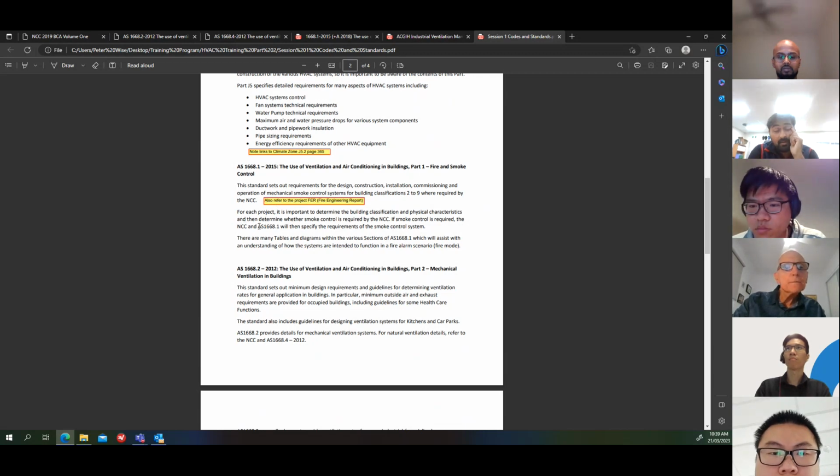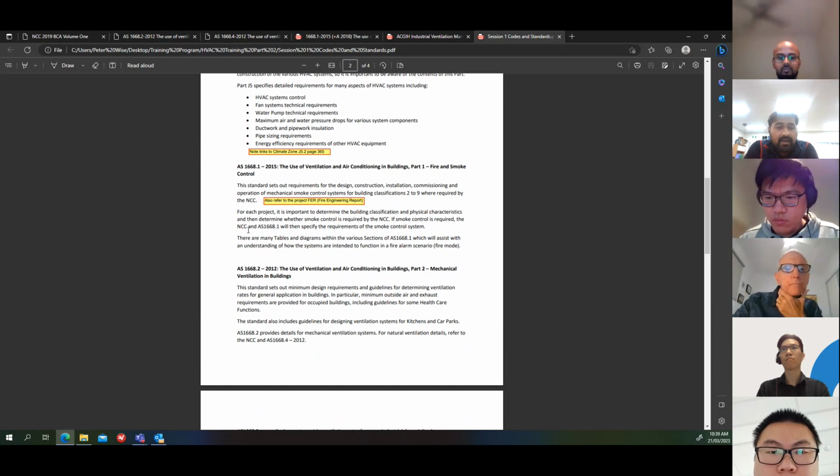So for each project, I have a question for you. If we're working on the DNC project, and we have a FER, fire engineering report, do we still need to refer to the fire and smoke strategy from AS 1668.1, or is just the fire engineering report enough? You have to refer to the NCC and AS 1668 Part 1, definitely, for smoke and fire and smoke control strategies.